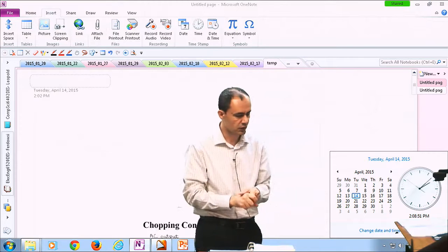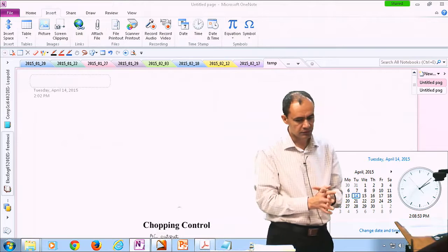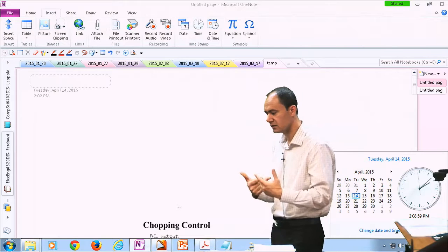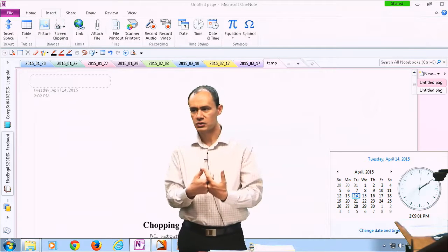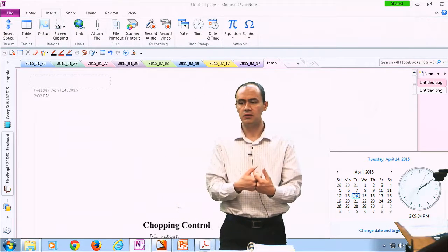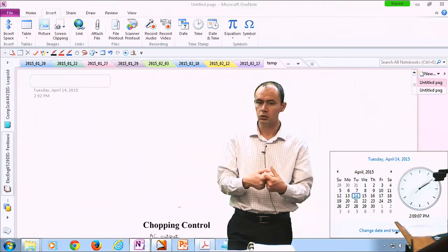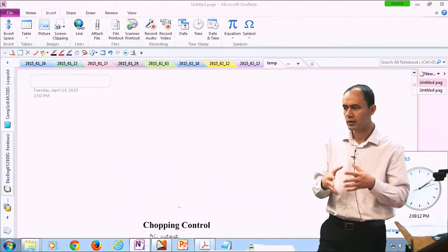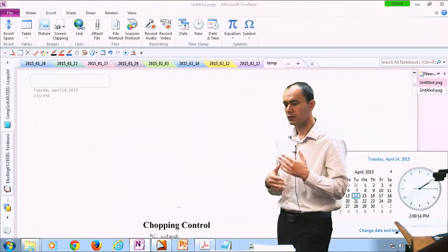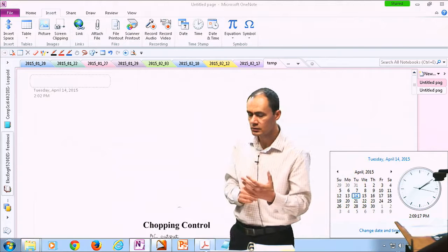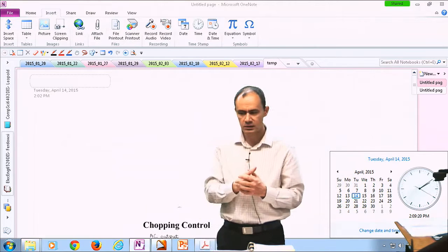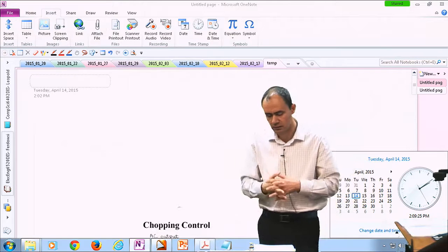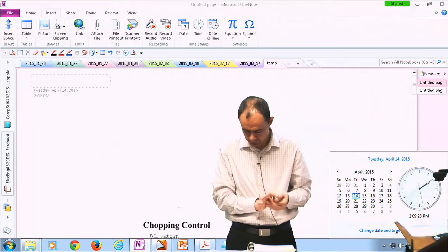For instance, if you want to compare a flying capacitor versus a diode clamp converter, the flying capacitor converter needs fewer switches, which is good, but at the same time, if you're looking at a 3-phase application, you need a lot more capacitors because each phase needs its own independent capacitors. Whereas the diode clamp converter, in addition to the switches, also has diodes, but the capacitors that you use could be shared across all 3 phases. So that's going to make your system a little bit simpler.